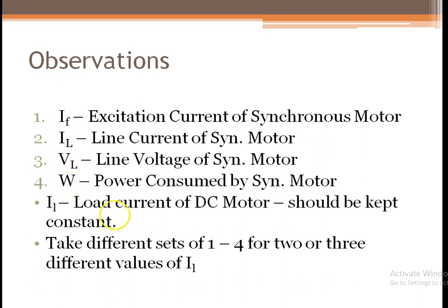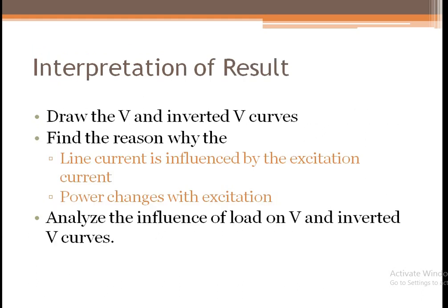After getting the power factor, draw a graph between IF and IL, that gives the V curves, and draw a graph between IF and the power factor you get using W, VL and IL. That gives the inverted V curves. Draw it for the different load values you have taken. Once the calculations are over, draw the V and inverted V curves in the given graph sheet.